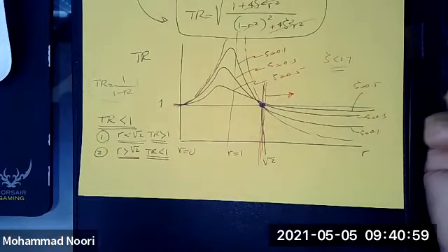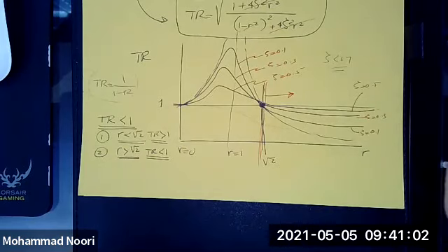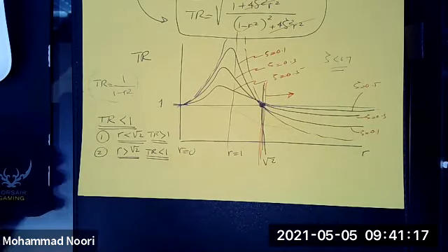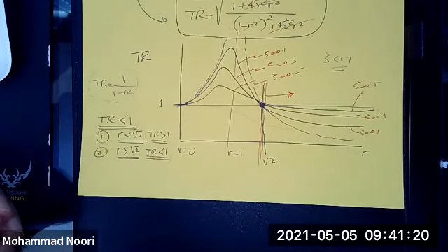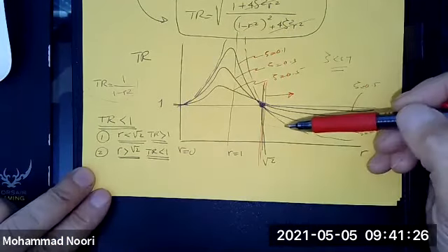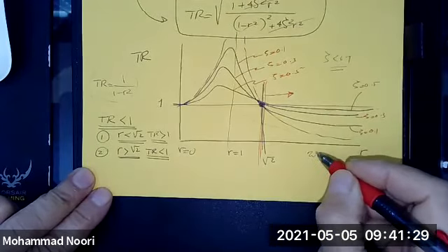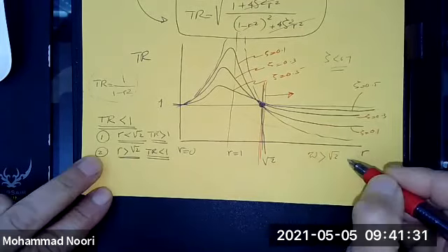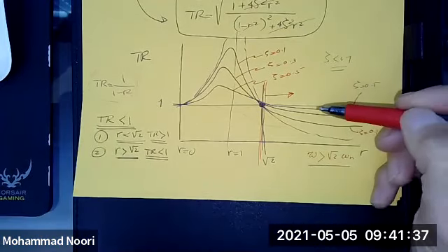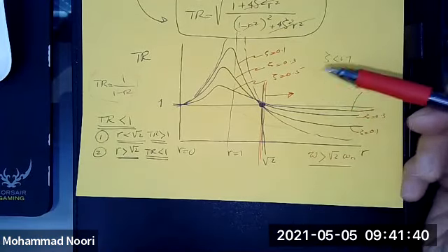That means if you have control over the frequency of the forcing function, a source of excitation, and the natural frequency of the system is fixed, in other words, you have an existing system subjected to a harmonic excitation, you've got to make sure that the operating frequency is always greater than square root of 2 times the natural frequency of the system, so that you reduce the effect of that applied load.